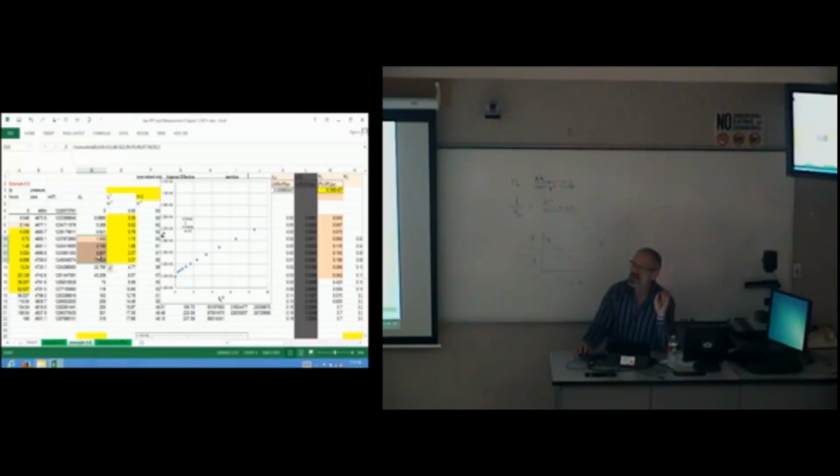I'm actually more comfortable taking the slope I'm getting from the square root of T sub A than with the MC plot. Because with the MC plot, I've thrown another parameter in there that is unnecessary. Now, I like the MC plot because that's the only thing that's going to give me P star, my extrapolated pressure.